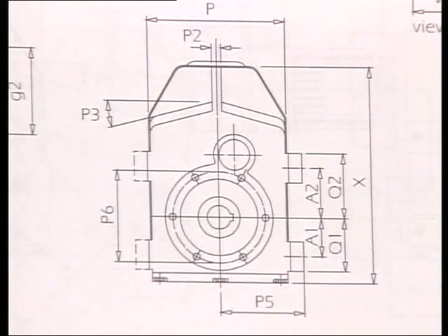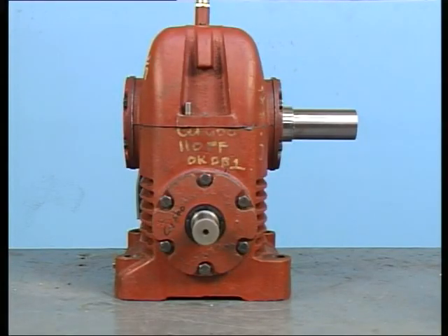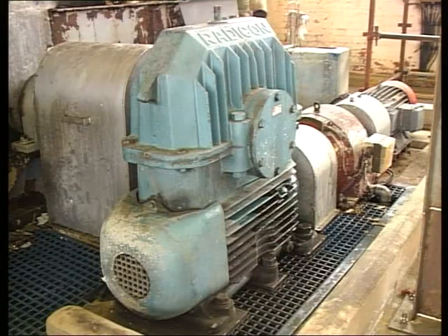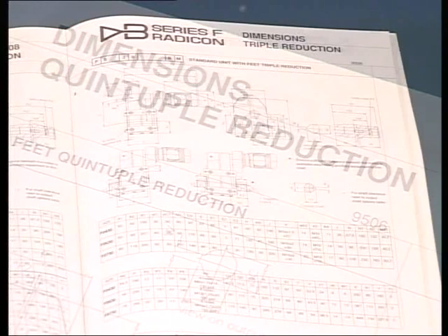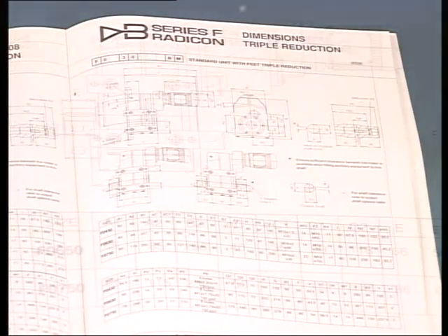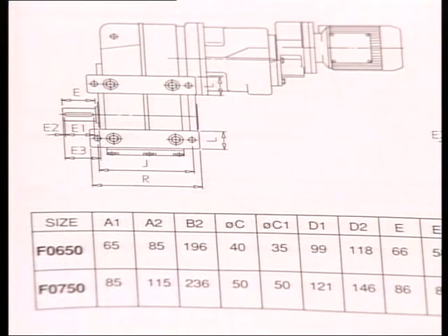Size may be given as the physical dimensions of the unit assembly, or, as is the norm with worm drives, size refers to the distance between the shaft centers. Some sizes are given in a unit's kilowatt capacity, usually referring to the rated output of the reducer when driven by the recommended motor. There are no set rules about how size is determined. Most often you will have to refer to the various gear manufacturers' data for this detail.